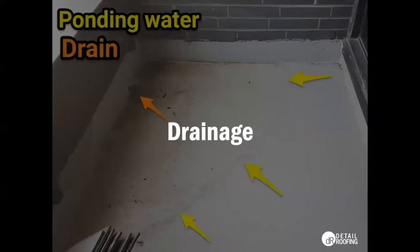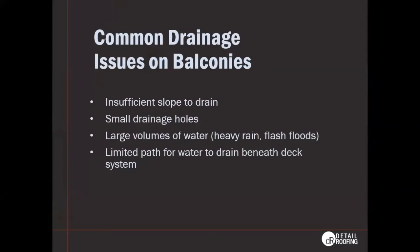So one of the main things is drainage. Some of the common drainage issues that we see on balconies could be insufficient slope to the drains that are on the roof surfaces. It could be small drainage holes if it's an overflow drain, large volumes of water, whether it's from heavy rainfall or flash floods or any major leaks that are occurring. Or commonly we will also see limited path for the water to travel below the deck system or the inverted system that's in place above the membrane layer.